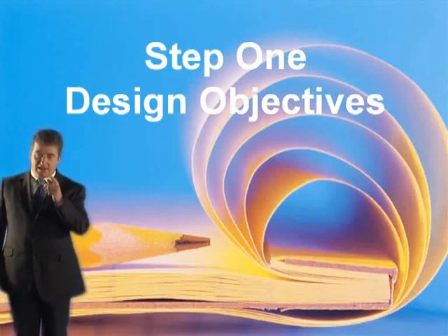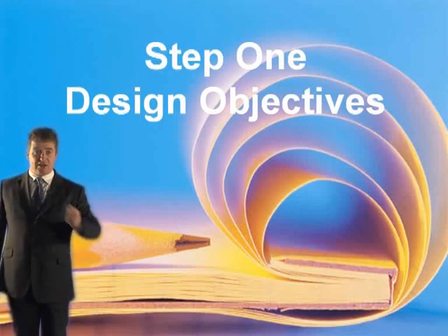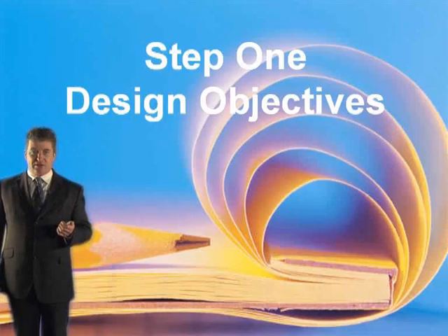Now the best way to carry out this check is to check the scheme using the 11-step guide, and when a step is not applicable you just ignore it. So let's carry out this check using the 11-step guide. Step 1, your design objectives. Well, these are specified as life safety. You've got to extract the smoke from the shop unit using a small reservoir before it can enter the atrium.